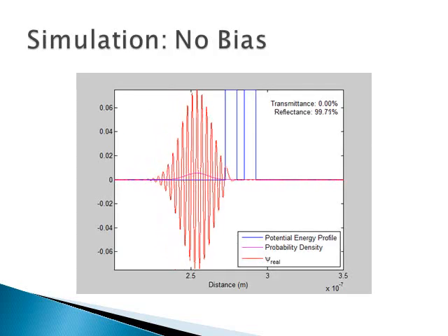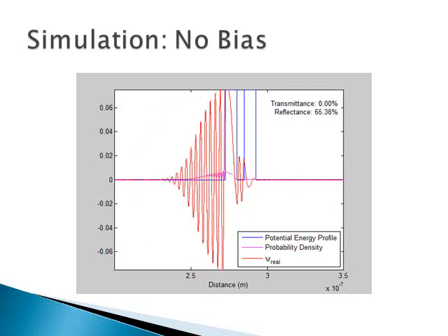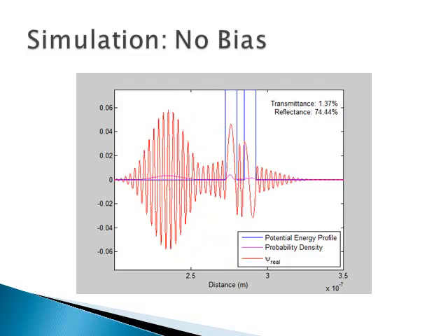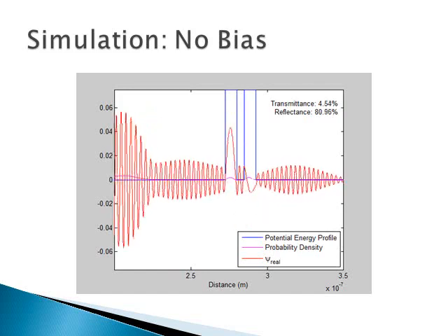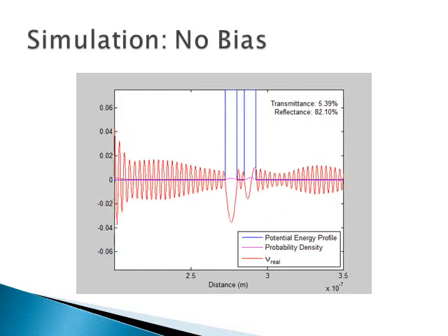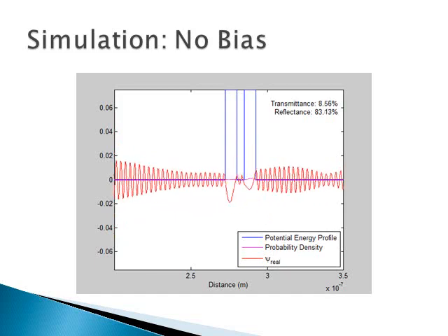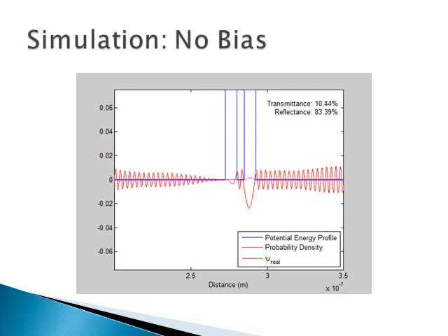In our simulation, we use material properties based on a silicon substrate with the barriers created by regions of compound silicon germanium. The barrier heights are 150 millielectron volts. The barrier widths are 75 angstroms, and the width of the quantum well is 50 angstroms. These values are taken from fabricated devices that have realized IV characteristics. For comparison, the wave packet is created as a 150 millielectron volt electron in a Gaussian envelope.